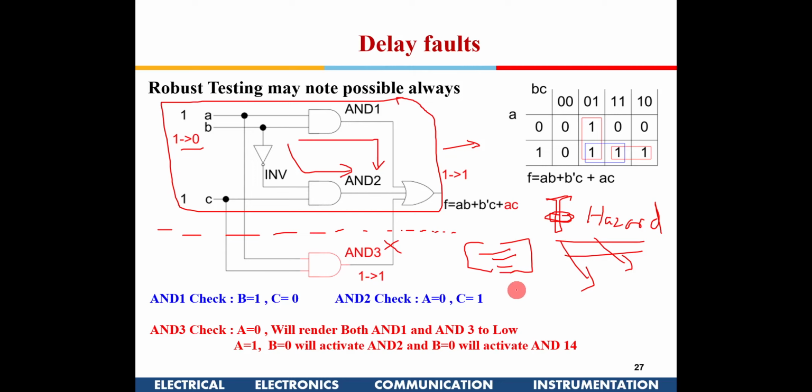when we list down all the faults, the circuit design engineer has to tell the test engineer, okay, there is some redundancy in the circuit. Please don't waste your time, because a test engineer may not know this is a redundant circuit. Whenever a redundant portion is incorporated by the circuit designer, he needs to tell the test engineer, okay, I have got some redundant portions in the circuit. Please take care of that. Don't include that in your fault list.